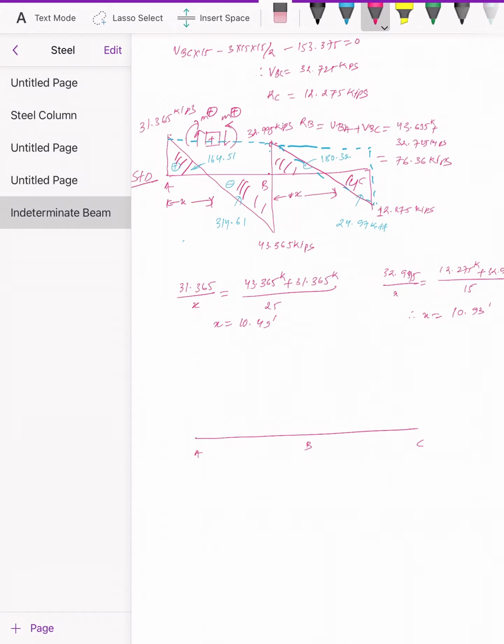Now before we start, how is your curve going to go? This is linear, so we have our bending moment diagram as a parabolic distribution. Look at the slope: it is highest at point A and it's decreasing.